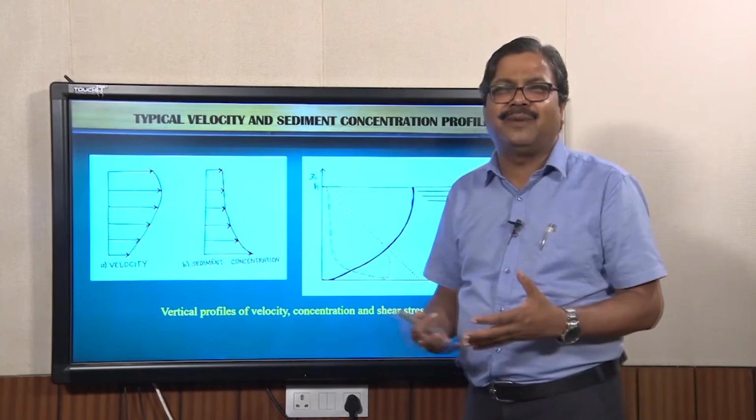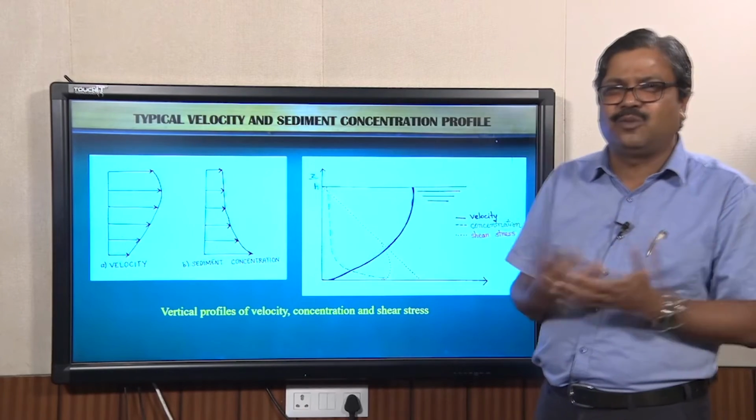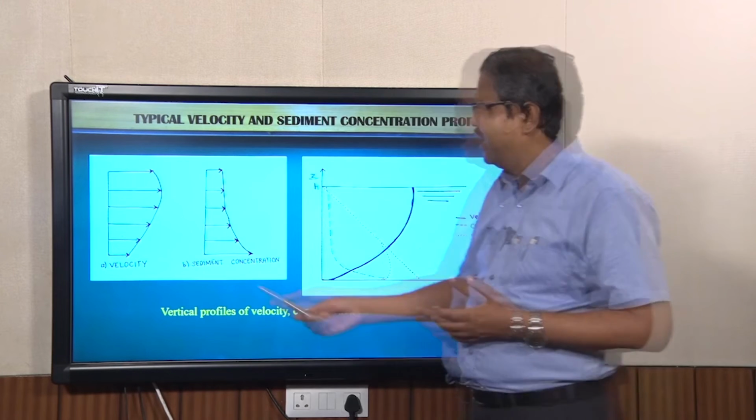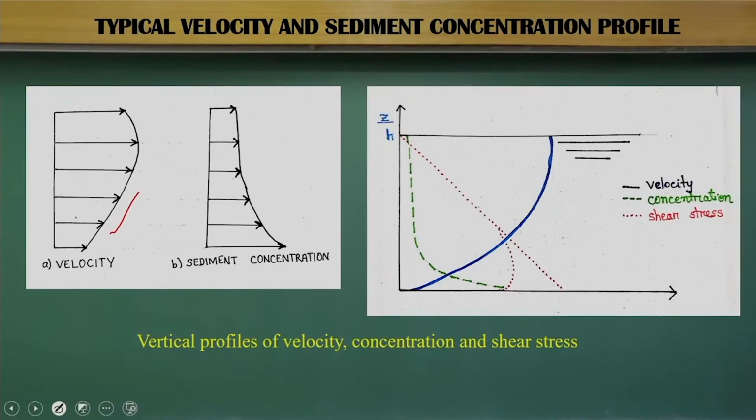If you look at a typical velocity diagram given in any textbook of river mechanics, they say the velocity follows a logarithmic distribution, and sediment concentration from the free surface follows an exponential decay function. But does it happen for the Brahmaputra River? No. Most river mechanics books consider this variability in terms of velocity distribution and suspended sediment concentration.